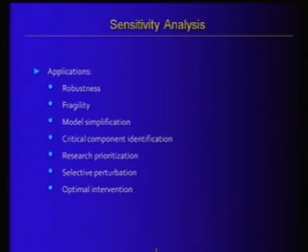Also, many times from data that you obtain from experimentation, you try to estimate the parameters of the system by using estimation techniques. You may not care to estimate parameters that the system is robust to, because no matter what the value of these parameters is, the output will be the same, more or less. But you are very much interested in estimating the parameters that the system is fragile to, and you have to spend a lot of time estimating these parameters very precisely, because small variations will create large variations in the output. So this is very important.